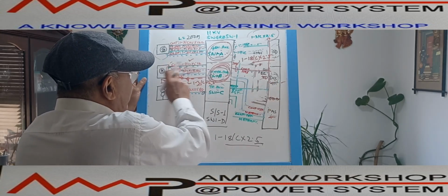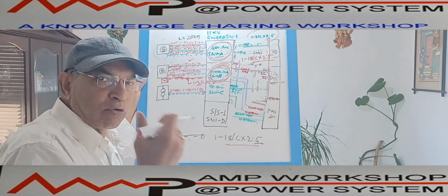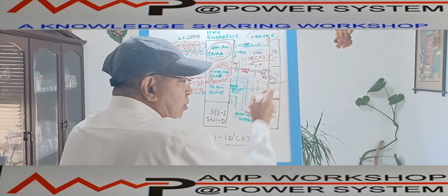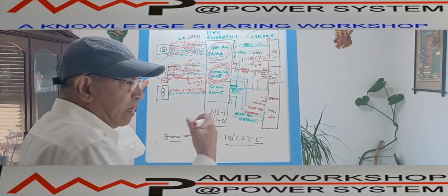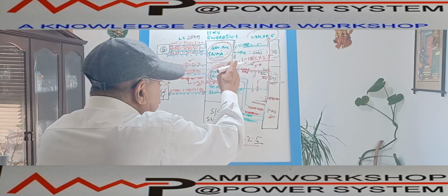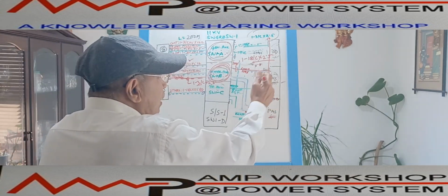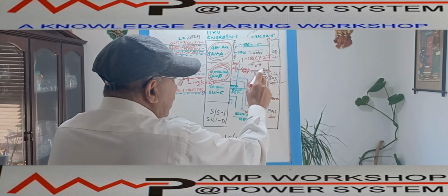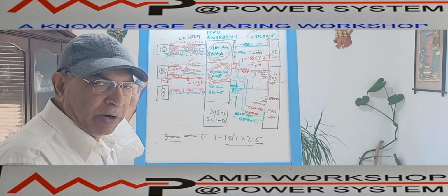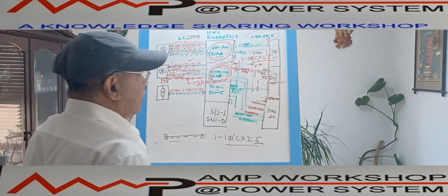As the winding temperature sensor signal comes to the generator panel, from the generator panel we can copy this signal to the DCS. Motor temperature high, bearing temperature high, circuit breaker on, circuit breaker off, circuit breaker protection, motor feeder protection operated, motor feeder trip circuit healthy. All these indications we can bring into the DCS. So this 18-core cable carries the on and off command control as well as various statuses of this panel.